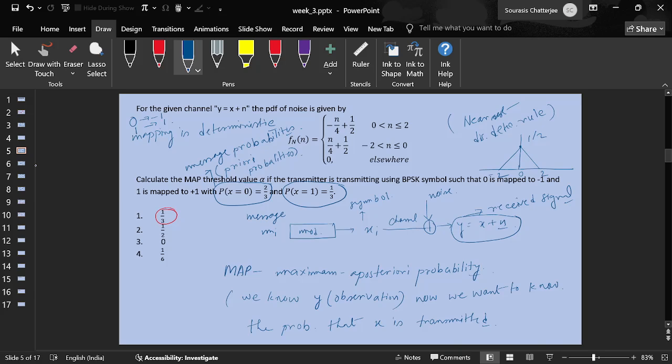There is one issue here. In the question, it should not be x here; it can be x here, but here it needs to change to m. Your messages are zeros and ones, right? Your message is this sequence. Only at the modulation stage are you mapping 0 to -1 and 1 to 1. So when I write x as -1 and 1, the probability should not be x equal to 0, it should be m equal to 0.